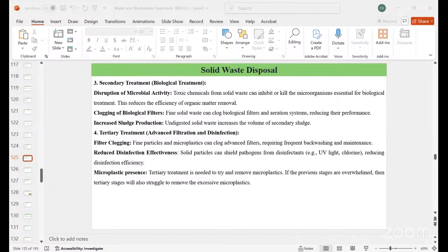So this is around 815 degrees centigrade to 1200 degrees centigrade. The waste is fed and incinerated at this temperature, and in this case it breaks down and decomposes the material into simple compounds, converting the waste into an ash residue and thereby significantly reducing the waste volume. It also handles a variety of solid and liquid waste, suitable for hazardous and non-hazardous sludge, with high flexibility in operating conditions. The main disadvantages are high energy consumption and the requirement of advanced air pollution control systems.